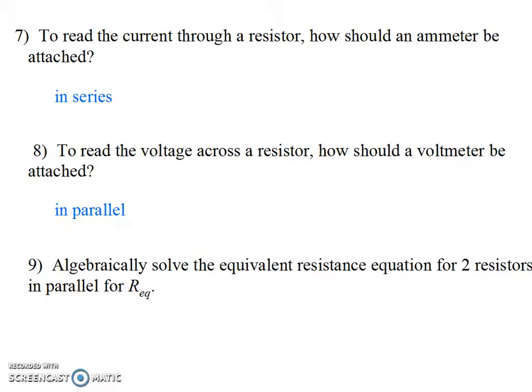All right, number 9 should have been really simple, because once you recognize that resistors in parallel are very much like capacitors in series, you can just jump right to the equation or do some very easy algebra to get this equation. It's R1 R2 over R1 plus R2, or the product over the sum. Again, if you'd like to box this in as a semi-new equation in a dashed line, you certainly can add it to your list, as long as you recognize it's only for 2 resistors and it's only in parallel. And it's only for 2.